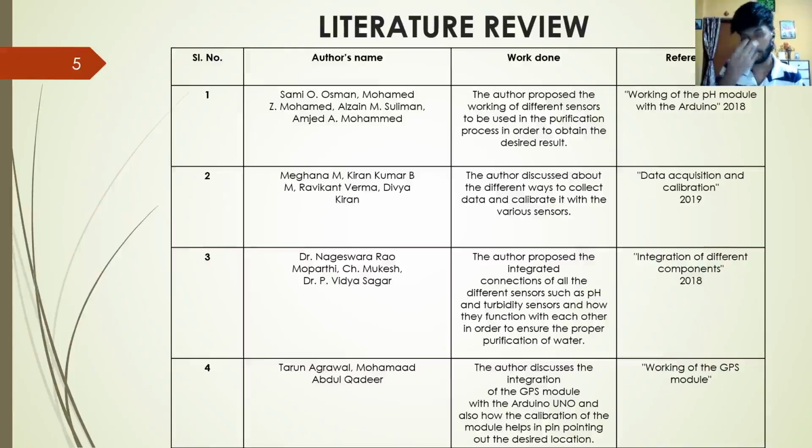As we all know, the working of the Arduino UNO is quite fine, but the pH module is quite complex, because when we integrate it with the Arduino, the module doesn't directly get the voltage and give the pH value, so we have to calibrate it. How the calibration is done, I will explain in the next slide. And from the next reference, we got the data acquisition and calibration.